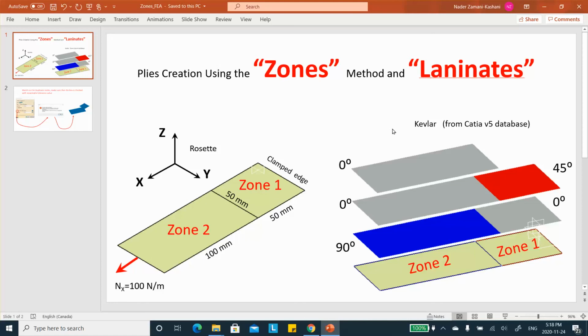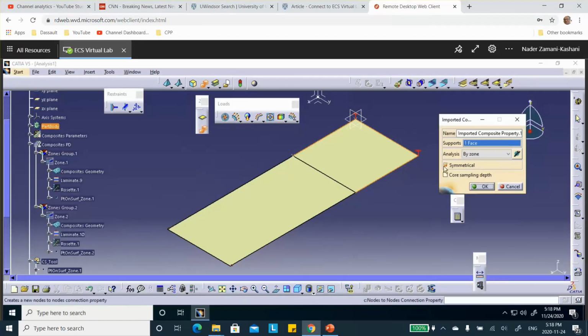But if this is stacked up all the way starting from the bottom to the top, then take the symmetry off. If we discussed this in the previous videos, if the surface was such that these things were symmetrically placed above it, for example, 45 above that plane, 0 below that plane or surface, etc., then you use symmetry. Otherwise, you stack it in this way on top of that reference surface. Okay, so I'll just leave it like that. In other words, I will take away that symmetry, so all stacked up like that, starting from the surface, up, okay?